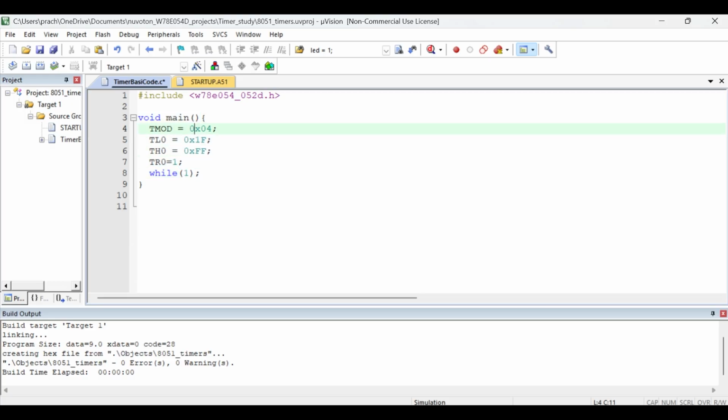So we will not load this because we want it to be 0. After the flag is set, we will declare an LED pin. And this is an sbit variable. And after the flag is set, we will wait till TF0. So we will wait here.